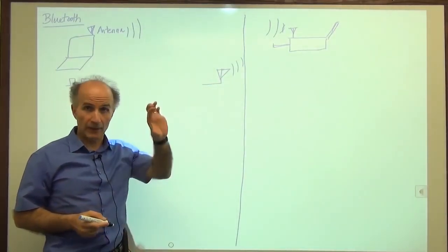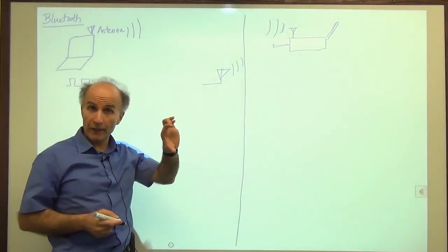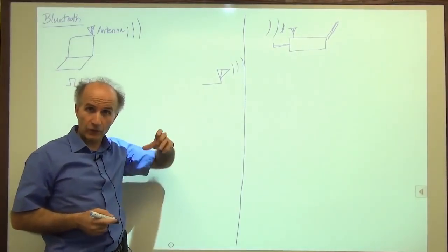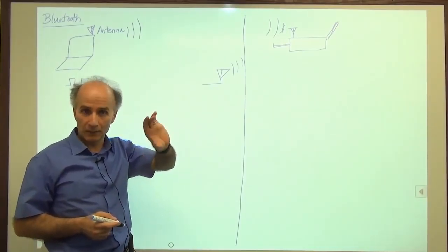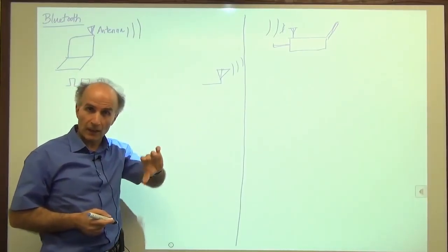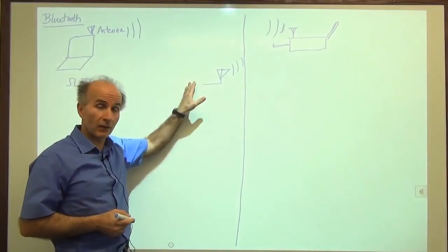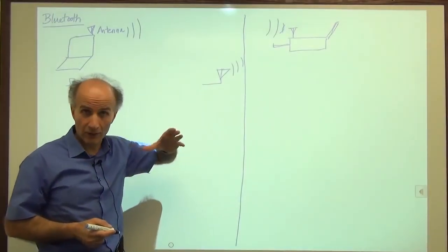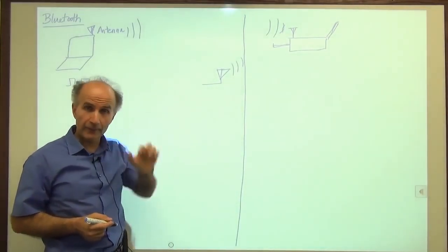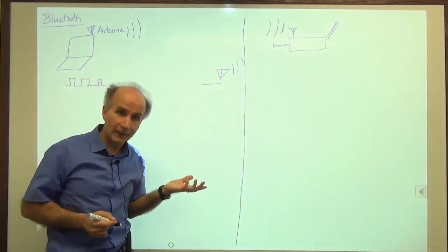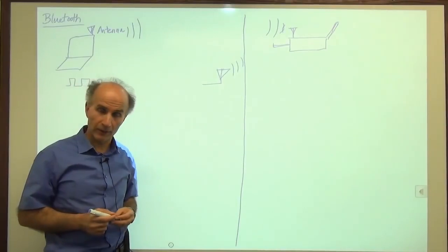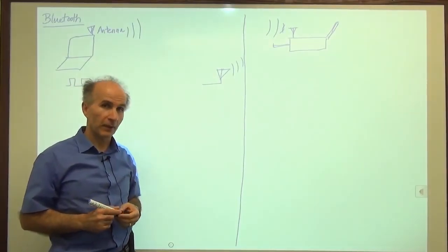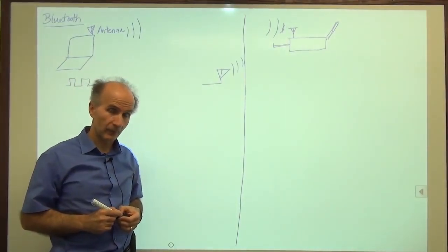So if the antenna is about this size, then the wavelength of the signal has to be on the order of 5 centimeters, 10 centimeters, maybe 20 centimeters, something in that range. But if the wavelength that's arriving here is much greater than the size of the antenna, then the antenna doesn't really radiate. It will actually operate like an inductor or some other component, but it doesn't operate as an antenna.